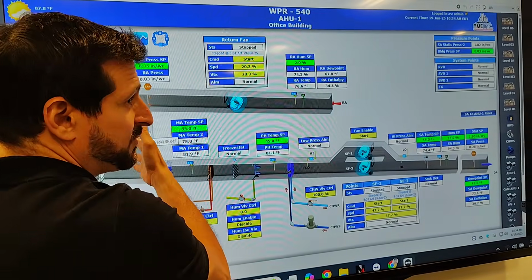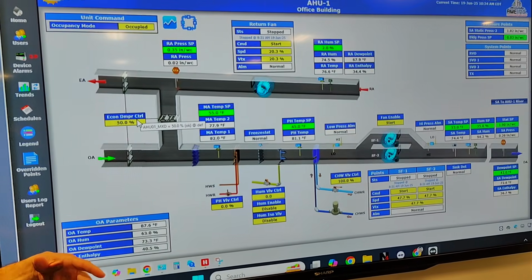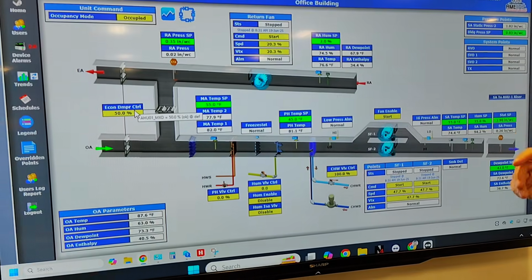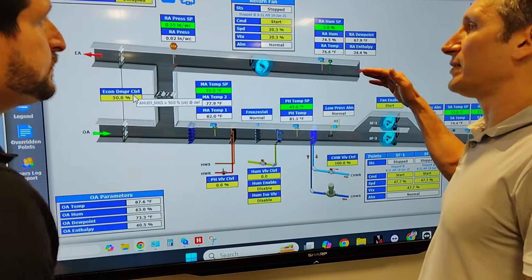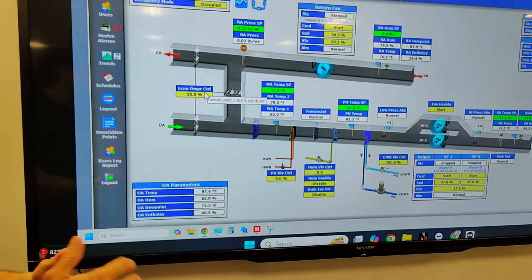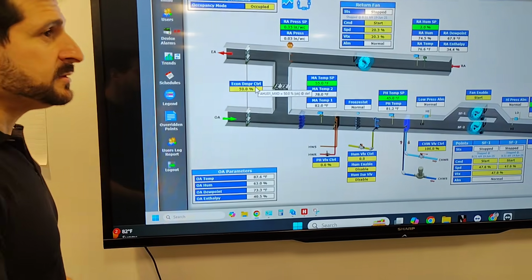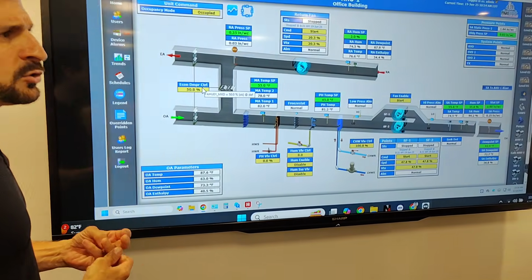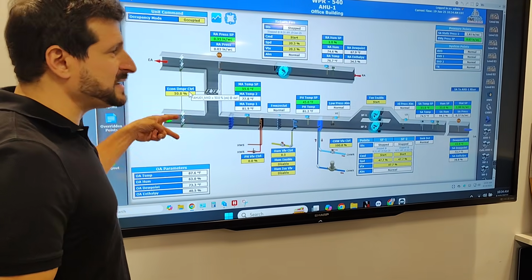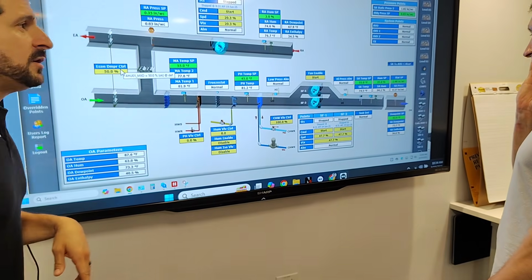You have to have some kind of foundational knowledge, right? And zero is likely the wrong move, right? Zero is like, I'm going to say 99.99% chance. And 10%. What we're trying to avoid is outside hot air coming into the building. So you do need that, though, because that's where your fresh air comes from. Yeah, 10%. 100% agree, right? But that 10% is not just based on the damper position. It's based on the damper position and the volume of the two fan setups.